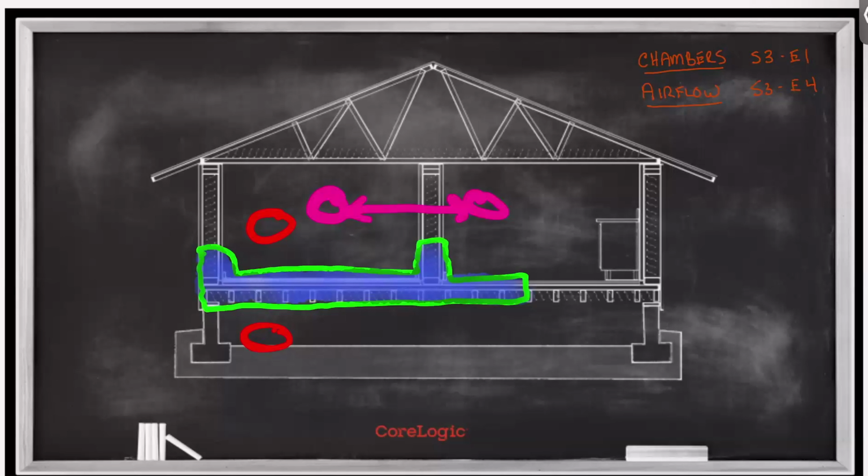If it is possible for me to move the air from one of these rooms into the neighboring room and back again through circulation, then these should be the same chamber, right? A drying chamber is not a wet room. A drying chamber is a series of rooms and spaces through which you can manage the air through circulation. So as long as there's a doorway or an opening between this kitchen and this living room, or whatever this is, these should be managed as the same drying chamber.